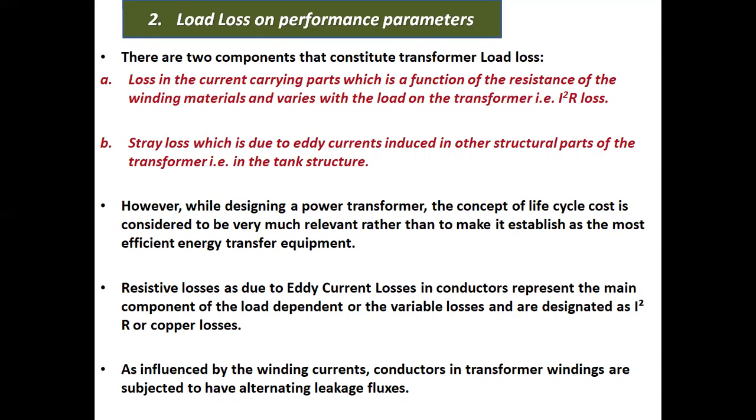Resistive losses and eddy current losses in conductors represent the main component of the load dependent or variable losses and are designated as I square R copper losses, as influenced by the winding currents.